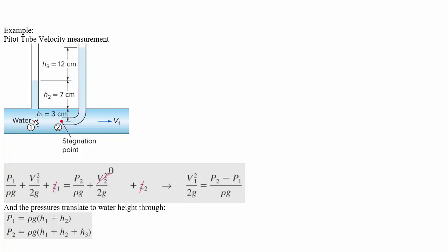Now you'll note that here, going up to this point, Bernoulli equation doesn't quite work, because from this point to the top here isn't really a streamline. So this is kind of a lateral motion along a streamline, right? So for this to really be a measurement of the velocity that works out extremely well, we're assuming that the velocity inside this tube is more or less constant along the cross section for us to make this calculation.